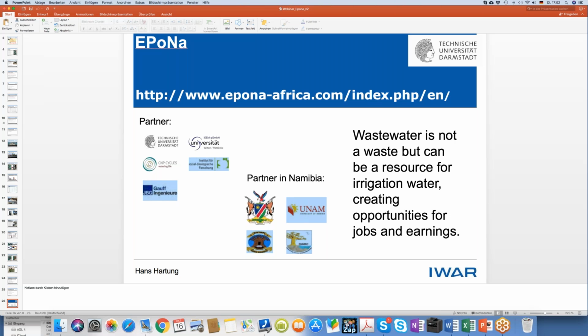First, the effluent standard when it comes to irrigation, the Jordanian standard 893, my colleague Ahmed can correct me if I am wrong, is very strict in regards to nitrate concentration when it comes to applying treated wastewater for irrigation purposes, especially restricted irrigation. And the other thing is the social acceptance of treated wastewater treatment plants.